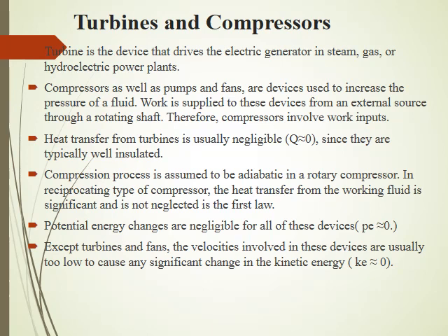Even though these devices function similarly, they differ slightly in the task they perform. The fan increases the pressure of gas slightly and is mainly used to mobilize a gas, whereas the compressor is capable of compressing the gas to very high pressures. Pumps, which are also very much like the compressors, differ from the compressor in only one thing: compressors handle gas or vapors, whereas pumps handle liquid. Otherwise, function-wise they are similar.